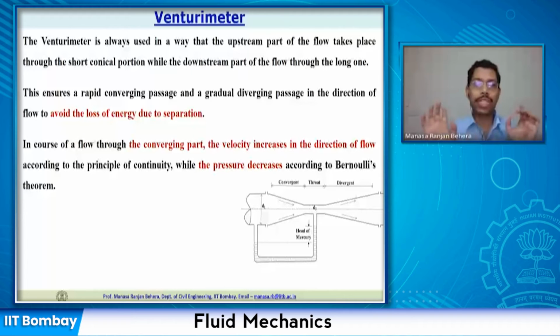The pressure is going to be just the opposite. Now if you look at this U-tube manometer, one end of that U-tube is attached to the pipe and the other end is attached to the throat, because we know exactly what the cross-sectional area of the pipe is and exactly what the cross-sectional area of this throat is. There is no variation, so there is no problem of exactly finding out the values. So these two are the points where the U-tube manometer can be attached.